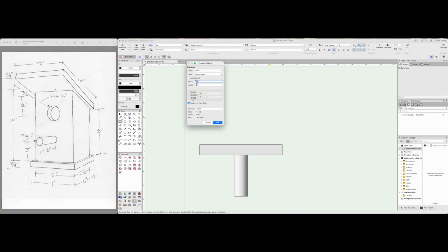So the width would be 3/4, the thickness of the material, and the height, and this is where your relationship with math can change. You could do the math in your mind of 5.5 minus 3/4 for the front and 3/4 for the back, because we're taking it that the face is most important. So the material would be inset here. That's a construction choice. Definitely something you might have a conversation with the designer or the props artisan.